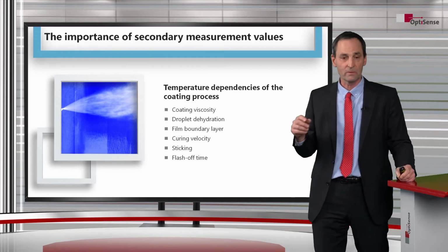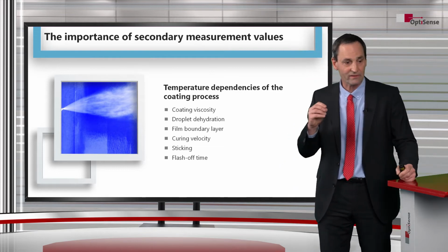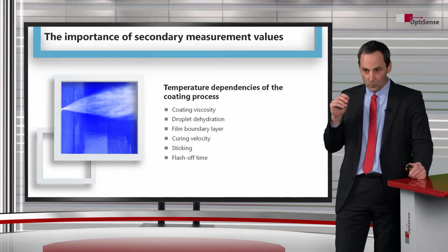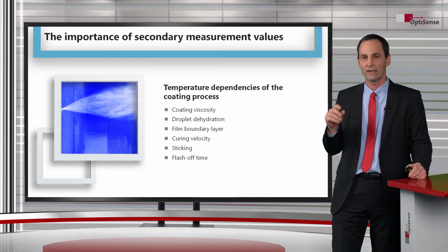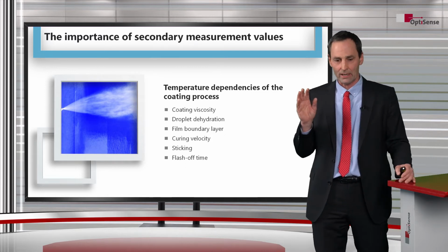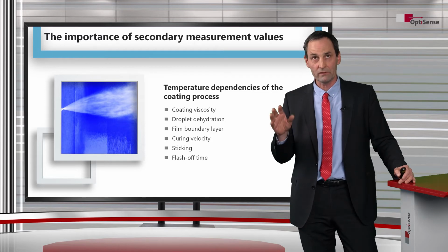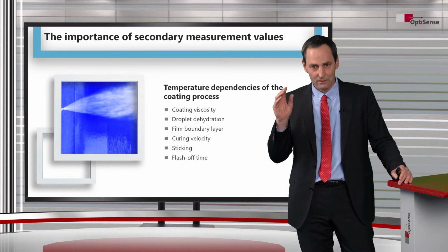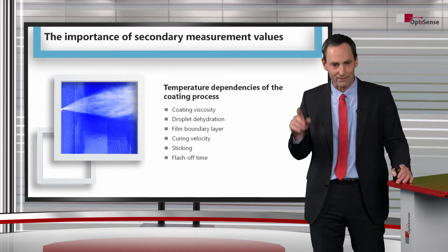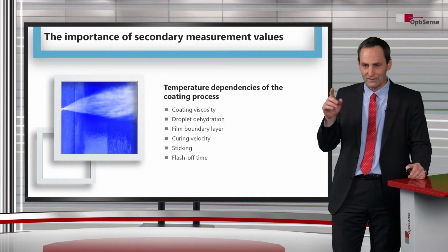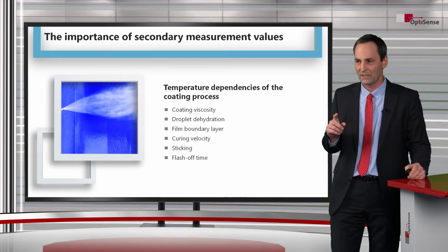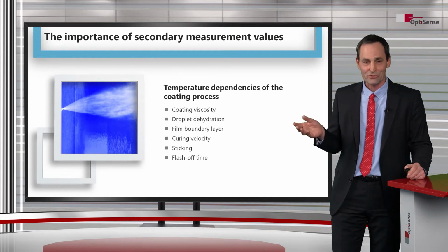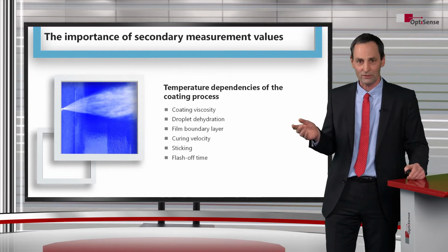So why shouldn't we store all this temperature data, which we still have also in this database, to really have the possibility to analyze in error cases? And I really could tell you, most of the applications where we have questions on coating thickness start with just looking at the temperatures, and then everything is nice, because you see that something has gone totally wrong meanwhile. So we see it here. Temperatures are really, really important and easy to measure.